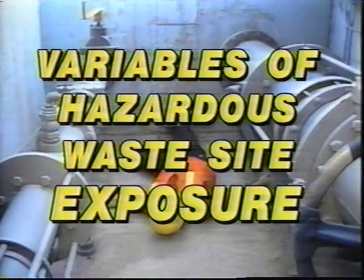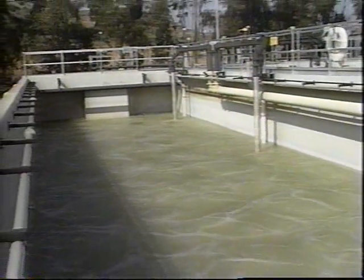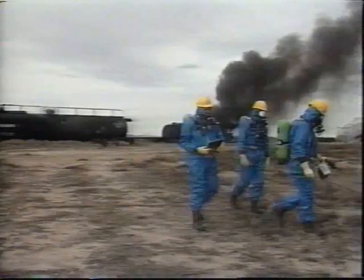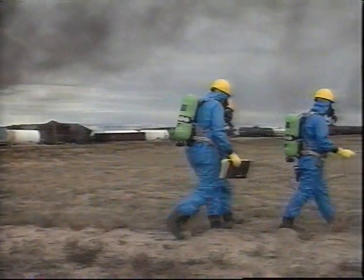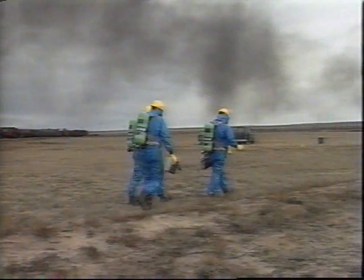Variables of hazardous waste site exposure. Complex, multi-substance environments, such as those associated with hazardous waste sites, pose significant challenges to accurately and safely assessing airborne contaminants. These factors must be considered when developing an air monitoring program and when analyzing data. Air monitoring should be conducted by trained persons familiar with the monitoring equipment and potential hazards.